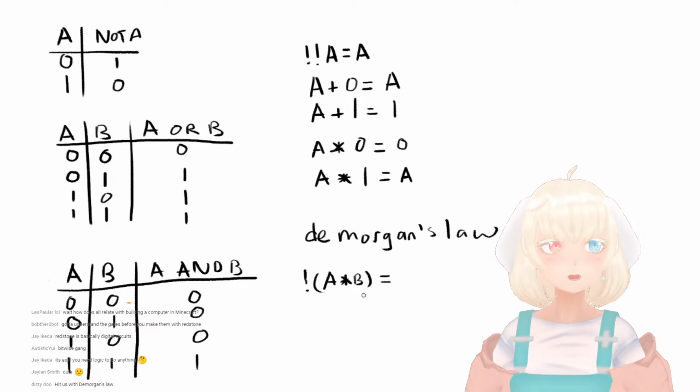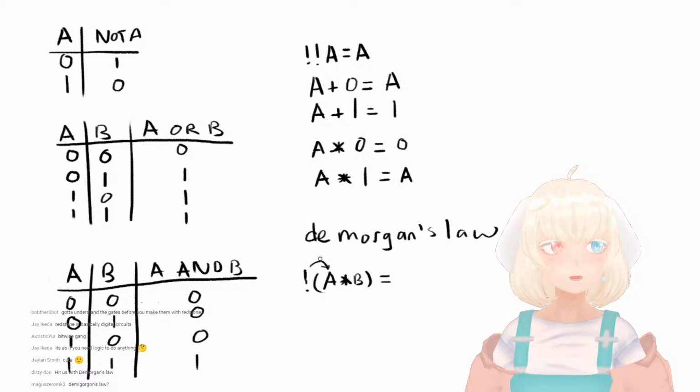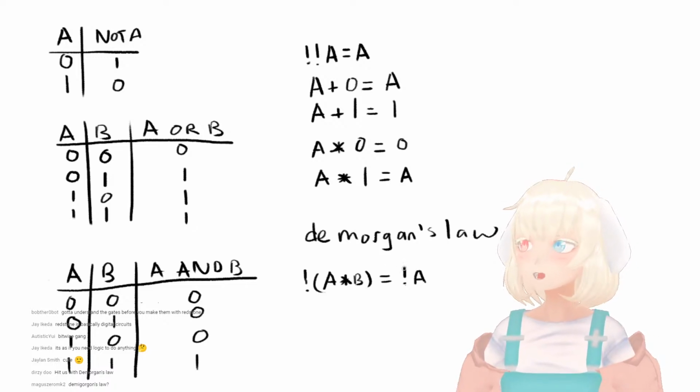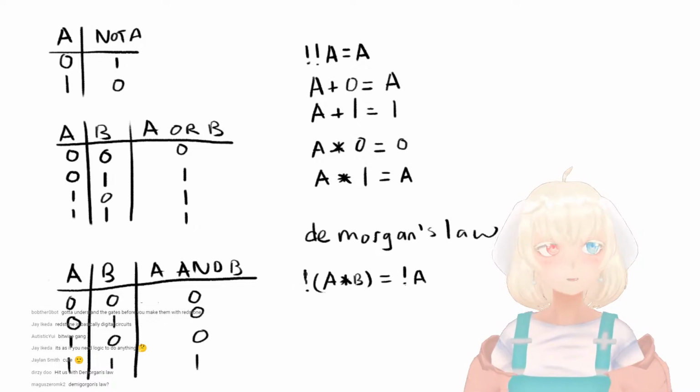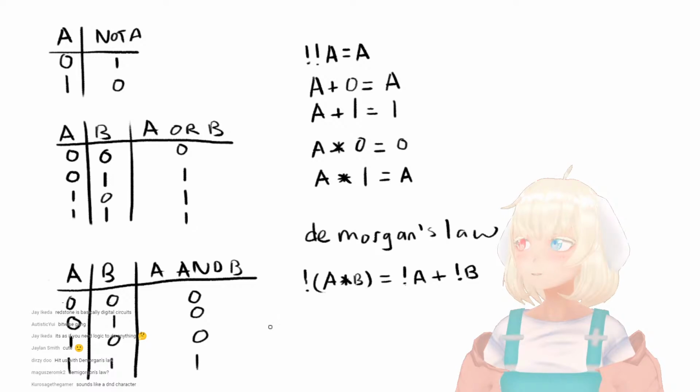This is kind of like mathematical expansion. You'd think that you'd be able to distribute NOT, right? Wrong. That's not how it actually works. So if you actually do out the logic tables, which we probably don't need to, it's a good exercise for y'all at home if that's something you're interested in. But we know that NOT (A times B), or A AND B, I should say, is NOT A plus NOT B. Kind of works out this way instead.